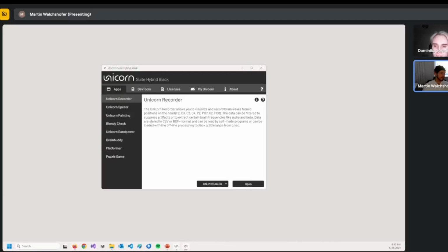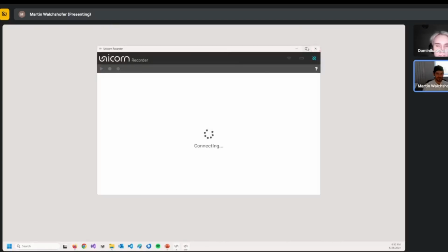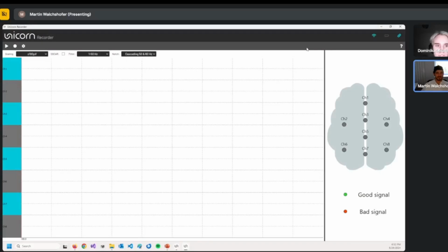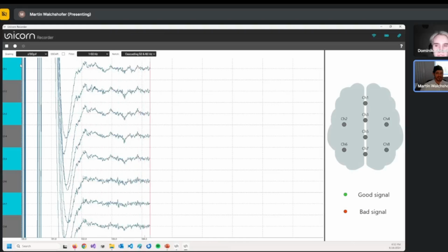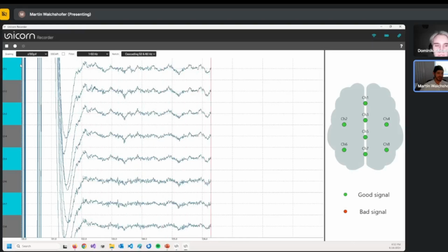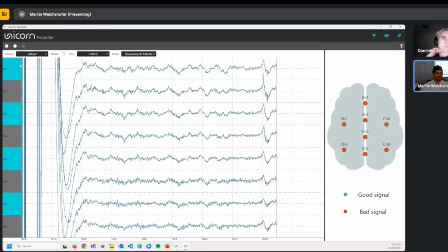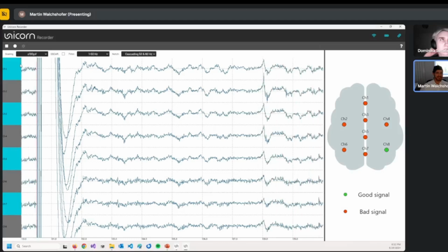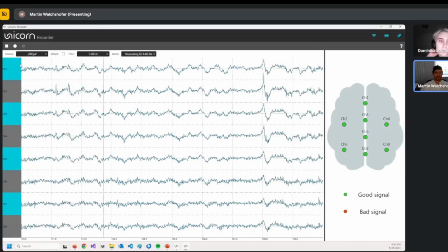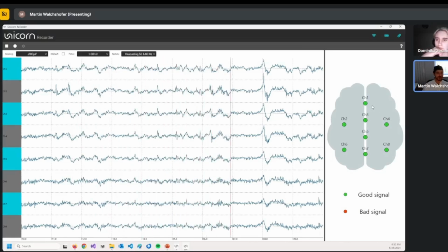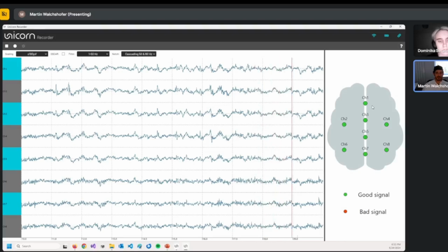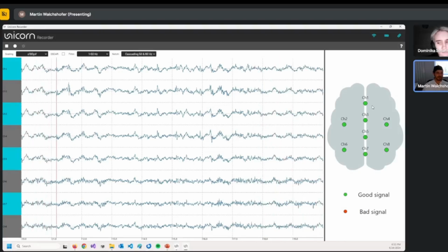Impedance is, especially if working with dry electrodes, a bit hard to estimate, because dry electrodes have higher impedance anyway and often are used with active amplifiers and so on, and then impedance is not the best guess, I'd say. And here we just check if the signals are in the correct amplitude and frequency range, and if so, we say the signal is good enough for BCI work.